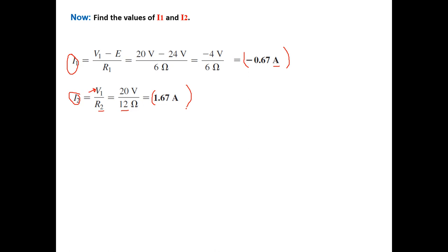So again, this is our nodal analysis method. Just study your circuit, determine the nodes, and pick a reference node. After that, apply your Kirchhoff's current law by assuming two things. One, the currents for the resistors are assumed to be leaving the node. Number two, when you're working with any node, you have to consider that the value of this nodal voltage is the highest.